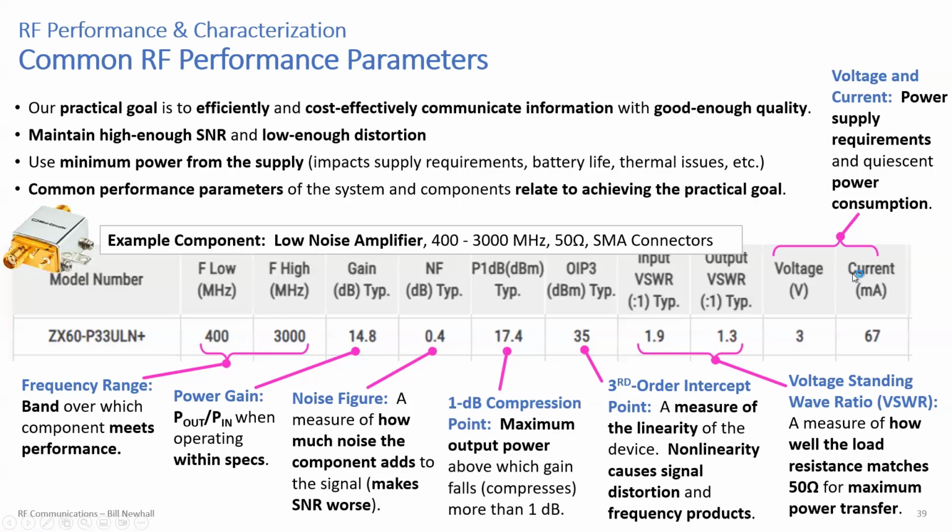So you will see these for many RF components. You'll typically always see gain. If the component affects linearity, you'll see IP3. If the component adds noise, you'll see noise figure. So these are the performance metrics that are typical. Okay. These parameters vary over frequency. So when you see this for this amplifier, you'll also see plots given for systems and components that show, well, at 400 megahertz, you might have a different noise figure than up at 3 gigahertz.